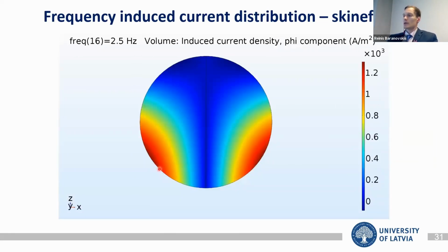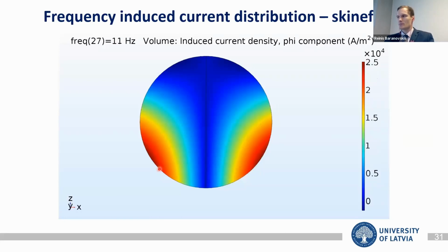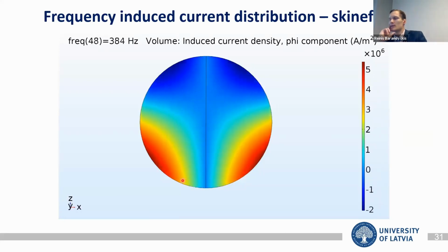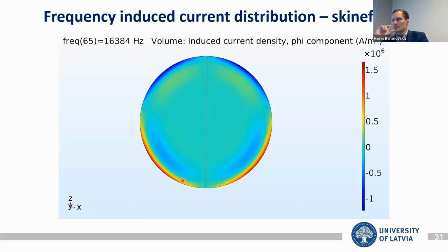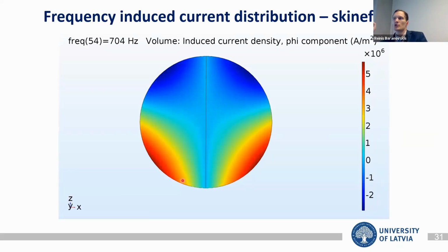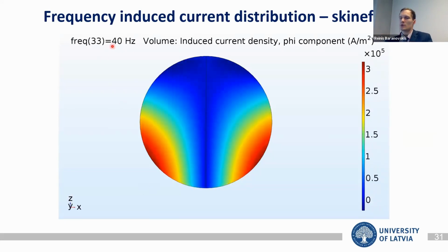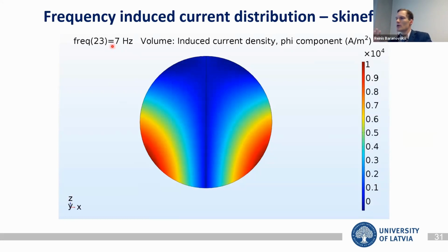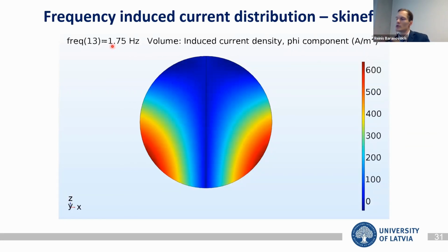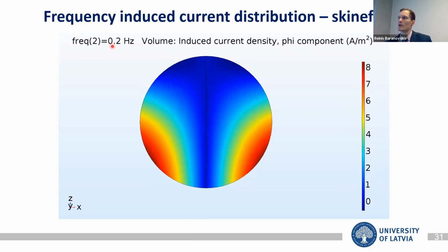And now I'm demonstrating to you this case, and we're looking at the induced currents only in the spherical object we're levitating. And when we change the frequency, we span here from a couple of hertz to multiple 10,000s of hertz, you can really see the current distribution drastically changes. And with high frequencies, it's completely expulsed out of the conductor.